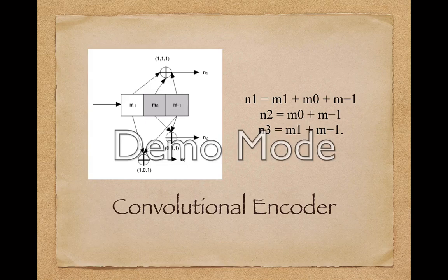Convolutional codes were introduced in 1955 by Peter Elias and have been widely used in a lot of applications since then. It is similar to the convolution we've learned, using several memory registers and modulo 2 adders. Each adder has an output.